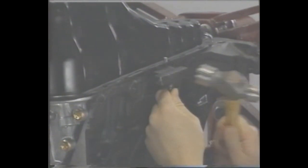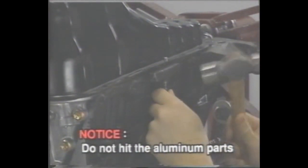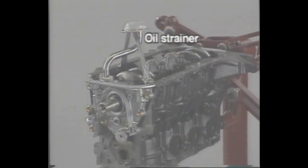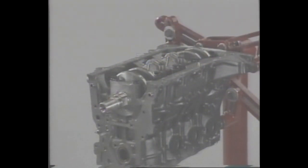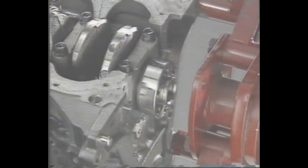Now let's look at the procedure for removing the cylinder block. First, disconnect the oil pan from the cylinder block using an SST. Then remove the oil strainer, the oil pump, and rear oil seal retainer.